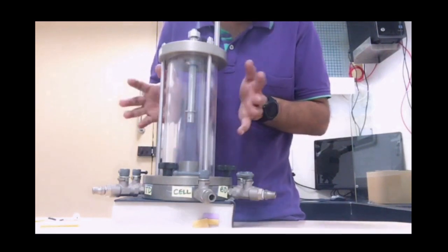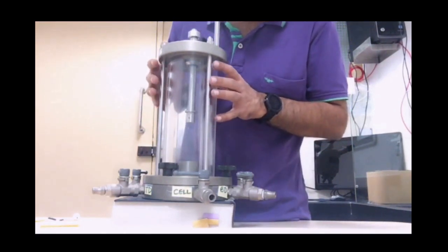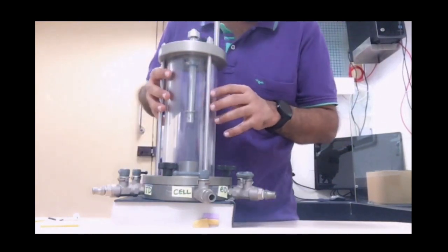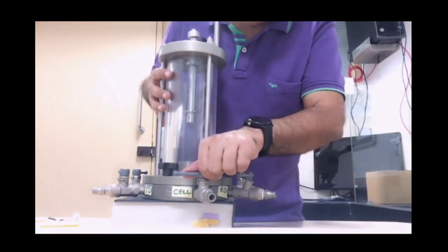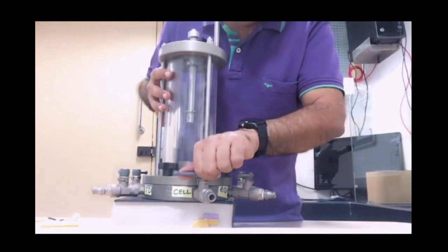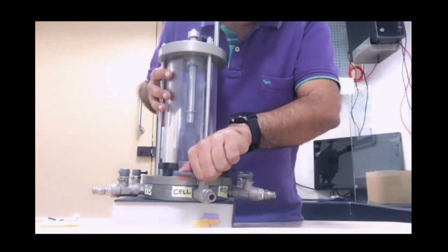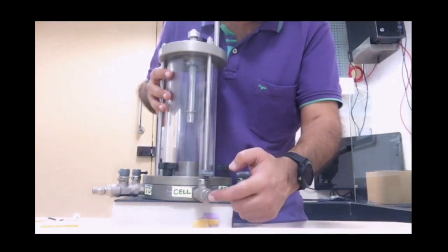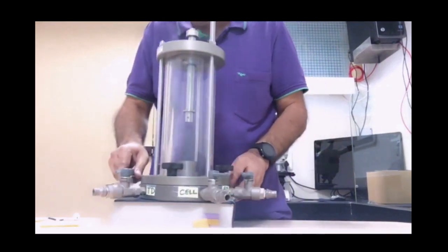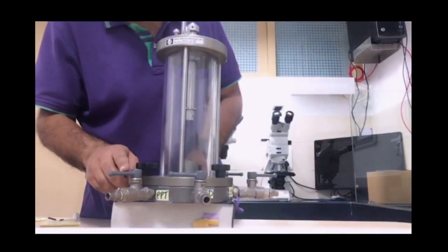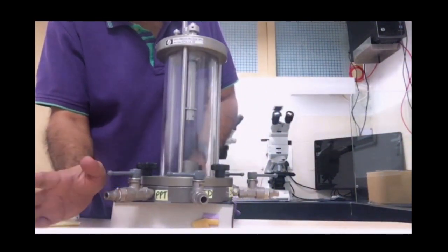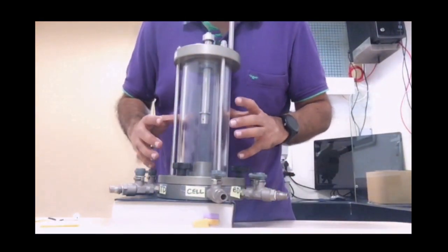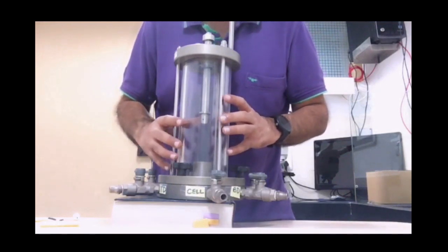So the first thing is, I know the sample is not saturated. Those kinds of things, I'm presuming are known to us. Although there are procedures for this, even before putting the sample on, I will not be able to discuss all this. But if it is known that the sample is not saturated, my first choice is to apply a lot of pressure, cell pressure, through here. Keep all my valves closed. I can, however, keep this PPT valve open because it's just a gauge. I'm not allowing any water to escape, right? So I can increase the cell pressure by a certain amount.